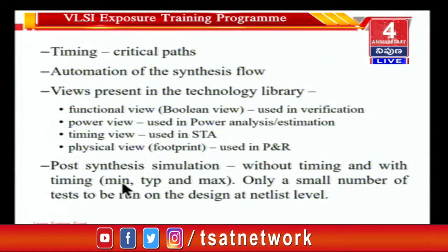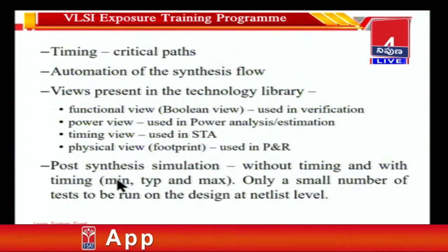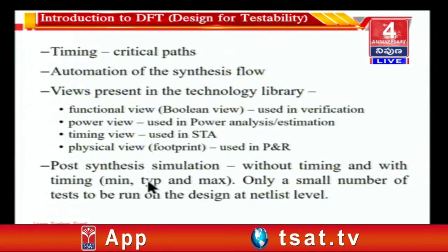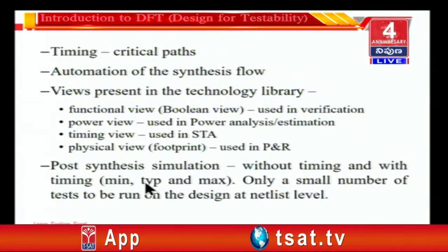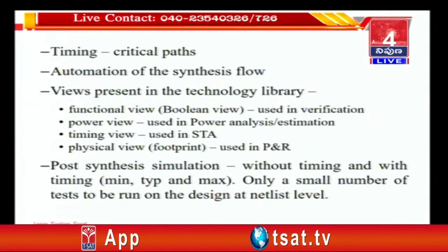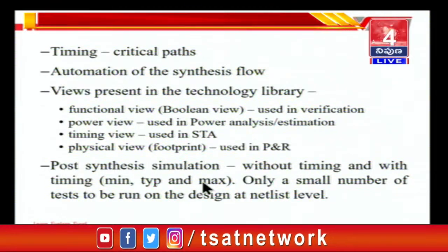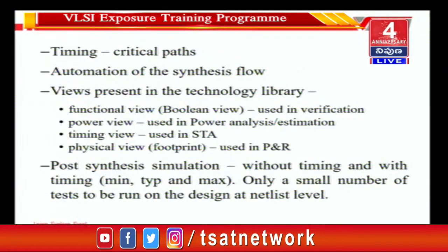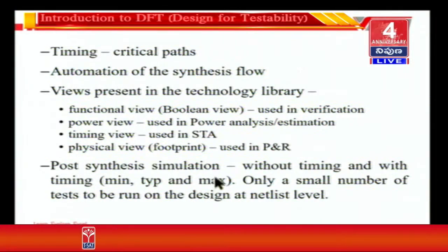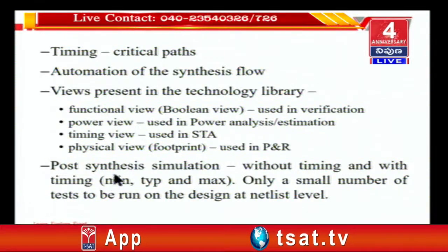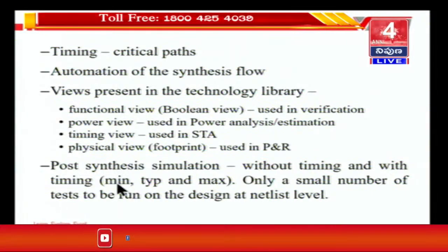Minimum delays are useful for checking if there are any hold timing violations. Typical delays will tell you whether the circuit is generally going to function at the required timing frequency or not, and maximum delays are used for checking whether there are any setup timing violations. Setup timing violations occur because of maximum delay, and hold timing violations, if at all they are going to occur, will occur at the minimum timing delays.